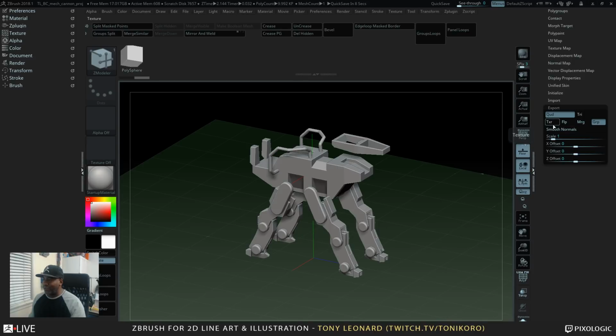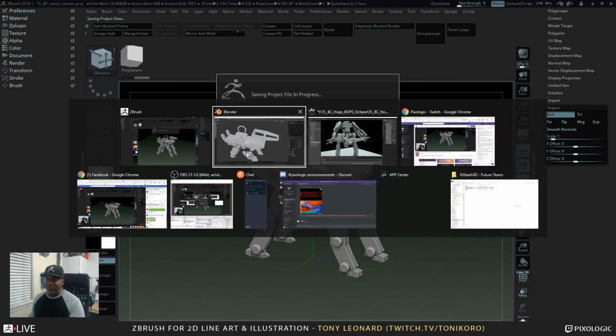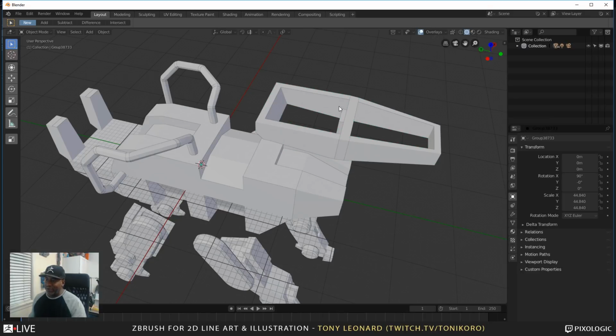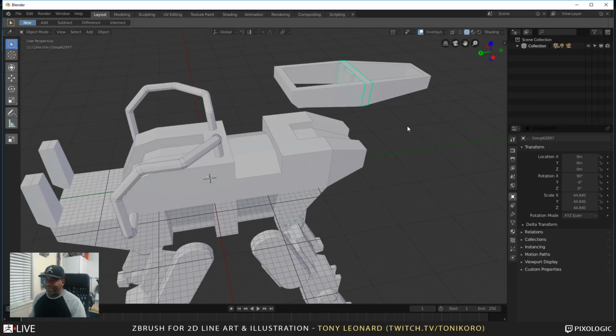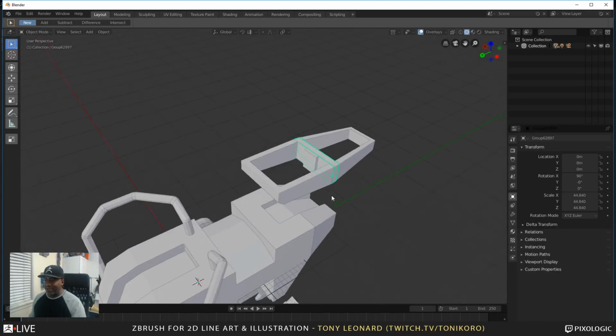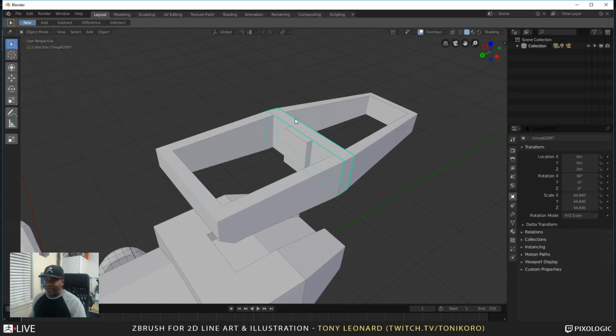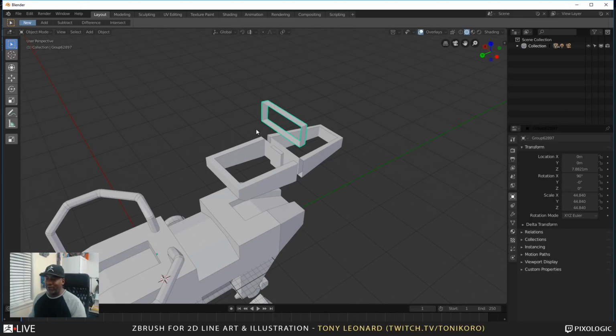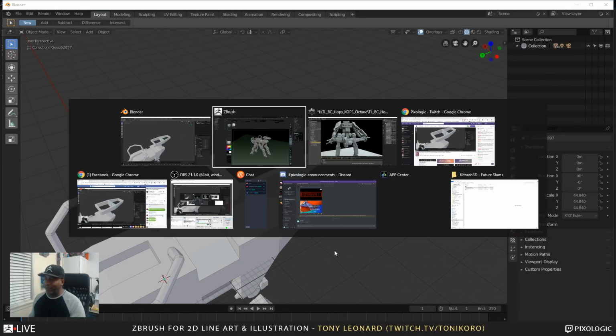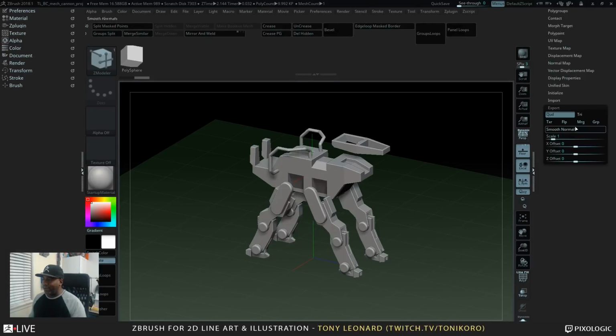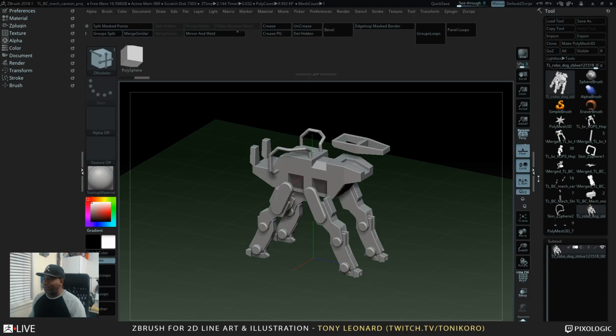The texture has to do with the shader, which really there isn't a material on it, but sometimes when exporting subgroups, everything comes in a little bit broken. So one of the first clicks that I made, I noticed, yep, this isn't right, because it'll actually part out the actual faces of the mesh, which is kind of weird, but it will come out like that, and that's not what we want. We want everything properly welded, I believe. So I'm going to go back and turn this off really quick, export as quads, and redo that save.